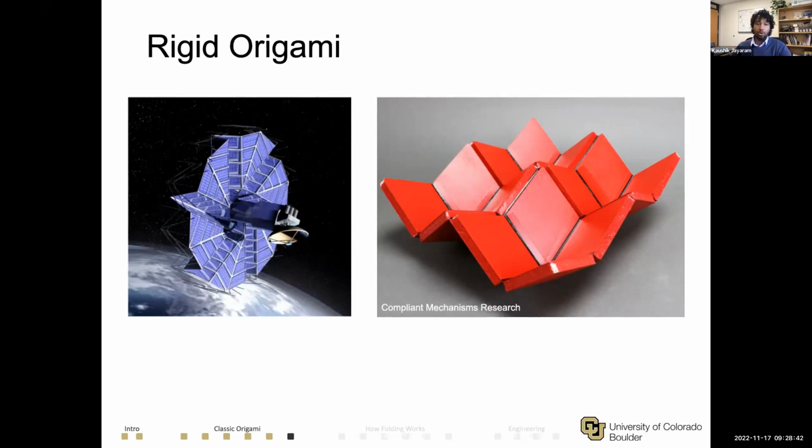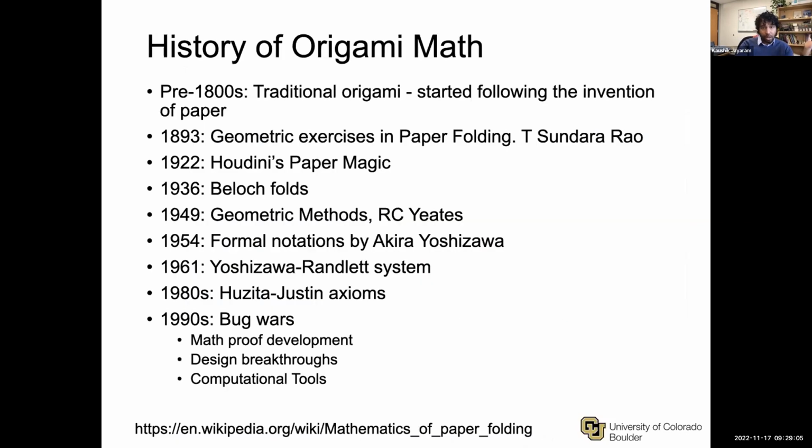The way I showed you is a laminate process for making these origami structures, but that's not the only way. You can still use rigid structures and make living hinges or flexures in materials and then still fold them up. The Compliant Mechanisms group at BYU has pioneered a lot of this work, and there are some really interesting results if people are interested in checking them out.